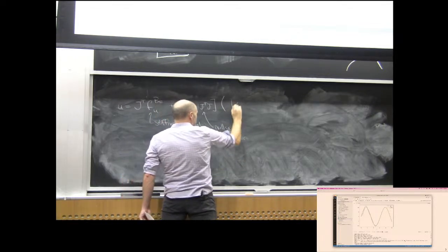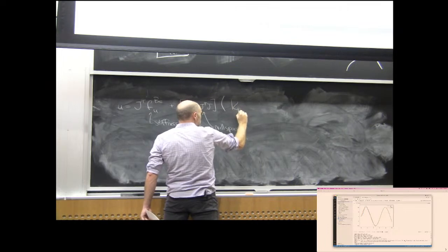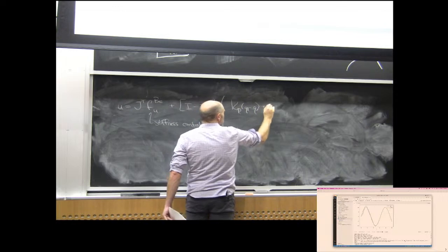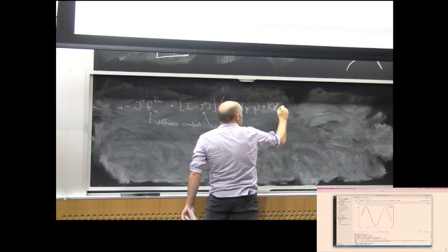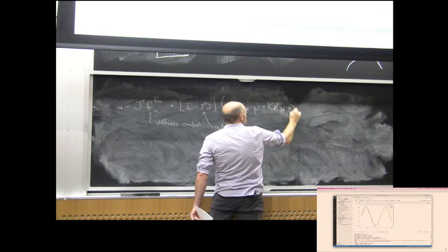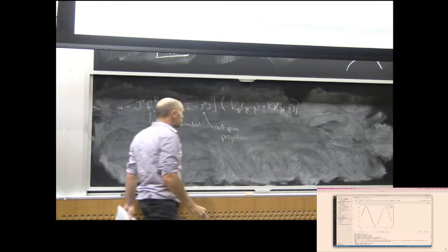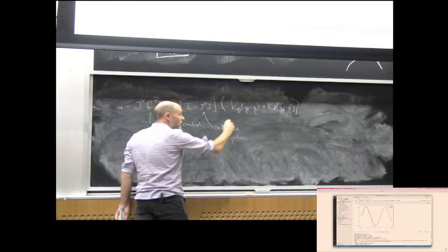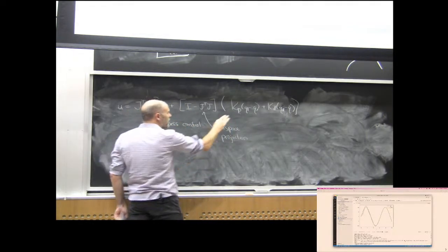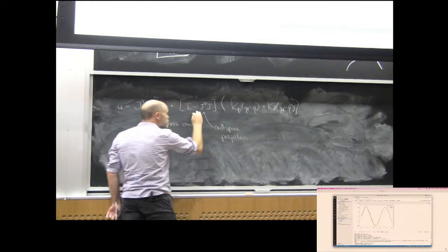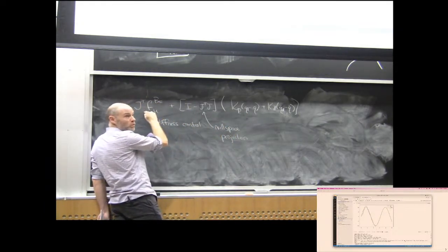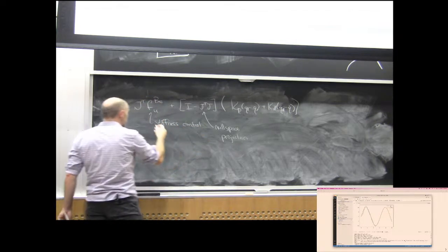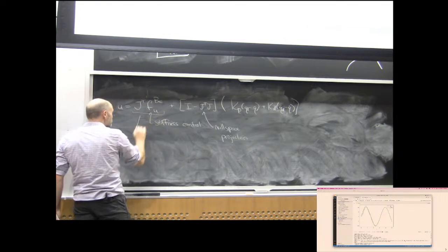And then write something like Kp (q minus q desired) minus q dot. Lots of symbols, but the point is you could write it like a PD controller in the joint coordinates and project it into the null space of this. So that's a really beautiful idea that says, in some sense, and the way people talk about this, this is the first priority task.